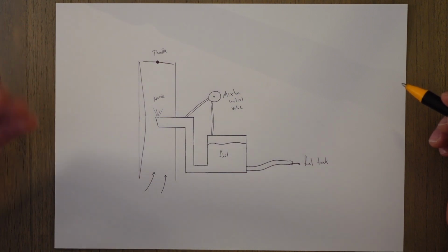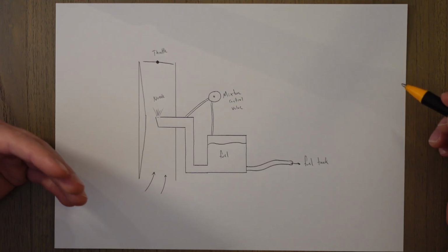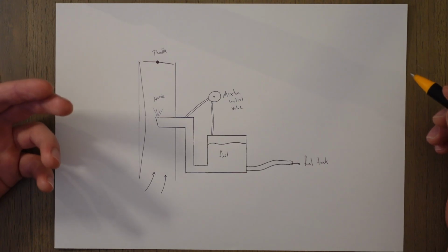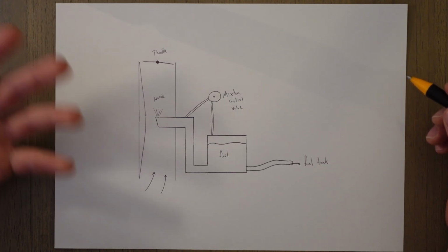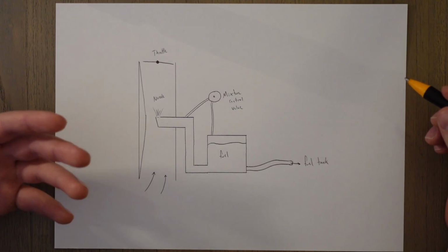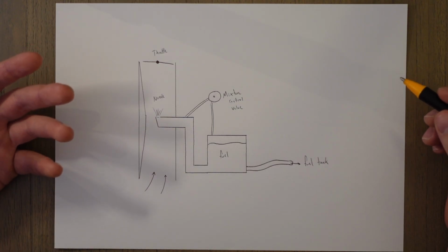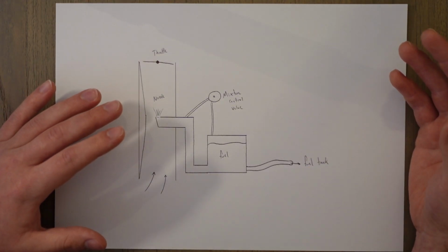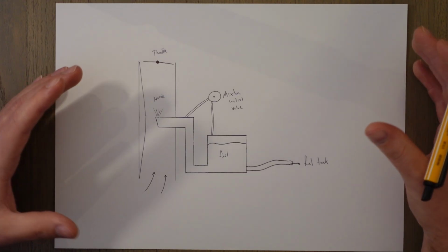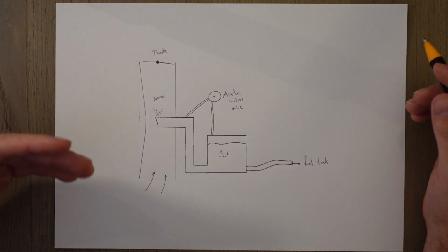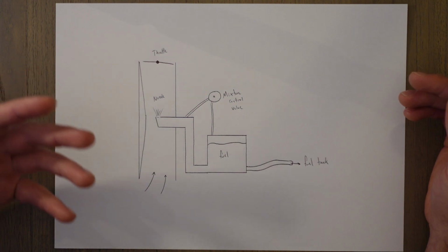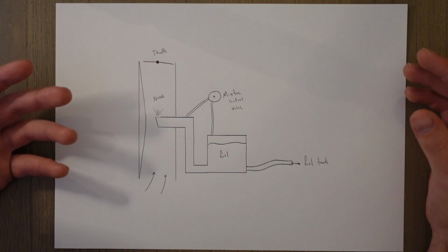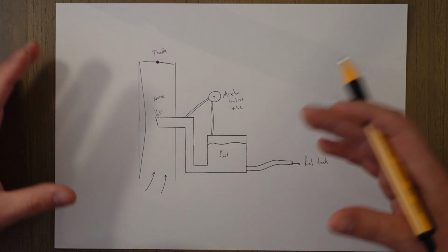This is why we can also reduce the amount of fuel, or lean out the mixture. If we're in the cruise, for example, with lower power settings than takeoff, we can lean out the mixture and fly with maybe 20 to 30% less fuel in the mixture. You may think that this will result in the combustion heating up, because it's the opposite of what we've just said. We don't have the excess fuel to absorb the latent heat, but it doesn't. This is because by adding less fuel, the combustion is slower and there are simply fewer molecules of fuel creating that heat.